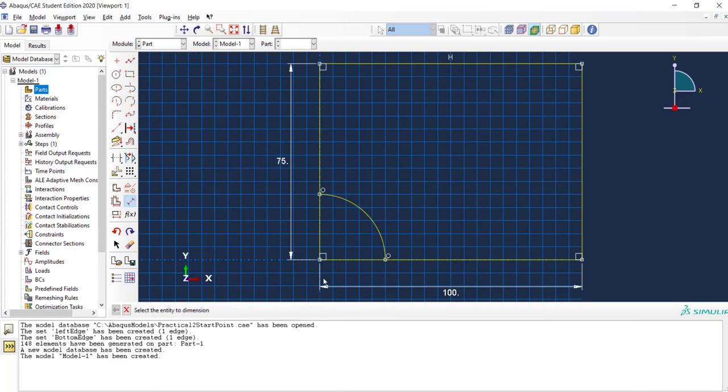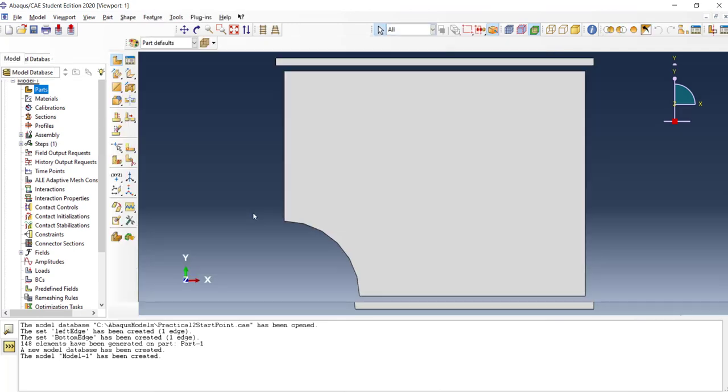And of course, if you want to be sure, you can always say that that should be 25, and then you're 100% sure it will not change, but not strictly necessary. Then use here the auto trim function that basically trims away anything you want, and I don't need these two lines because this is how my section should look like. And that's it, I'm already done with creating the section.